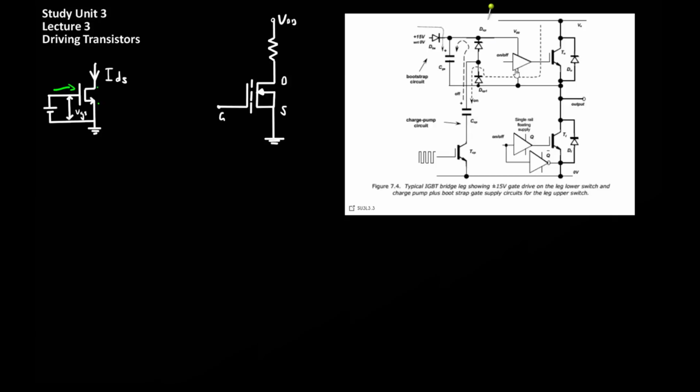This means that the high voltage required to switch transistors is supported through the charge pump circuit and these two diodes over here, which provide the VGG required for this gate. In combination, this allows a higher voltage to be supported over here, which is higher than the total supply voltage plus the required voltage for the buffer driving the top switch. The reason that these two circuits are used together is that startup is a problem when only using the bootstrap technique, and the charge pump circuit is required to provide a startup condition for the top switching transistor.